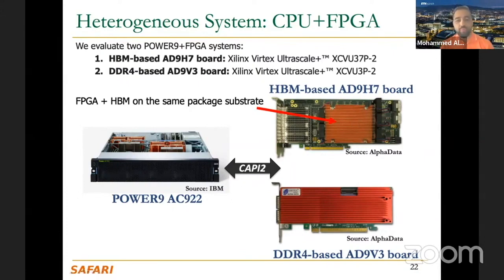So you have the chip located either in the same package or very next to it. So it's different from 3D stacked memories, but these memories have very high bandwidth, where you can fetch a huge amount of data with less latency to the FPGA logic to do the computation. We compare with another design that uses traditional memories, DDR4, and uses a Power9 IBM system to do the connection.